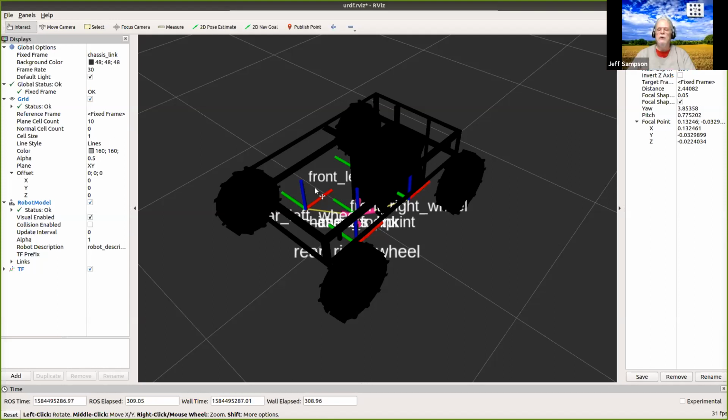And also keep in mind, if you're monitoring with RViz, you can turn off all the extraneous stuff. You don't need to see everything at the same time. The more stuff you can turn off, the less traffic you're going to have back and forth, so the better that's going to work in the long run. But back to the original point, yes, I like to put any control stuff right on your vehicle so it can run on its own, and you're just using RViz to say, go to this location and look at what's coming back, as opposed to having a base station running all your navigation software and trying to talk back and forth, because network issues will get you into trouble real quick doing that kind of thing.